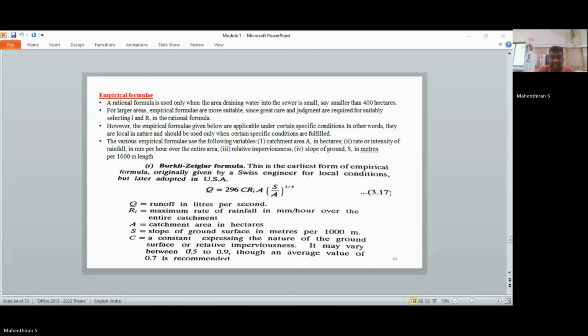Next, we look into the single rainfall intensity, which has been given as Ri. This formula uses one Ri value for the entire catchment, ignoring the spatial variation in rainfall. Now, average slope only. Here, the formula uses a single average slope. For catchments with highly variable topography, this may not be representative.